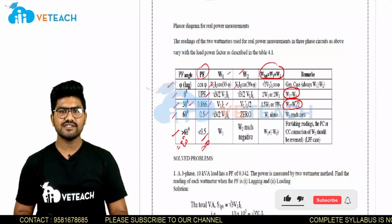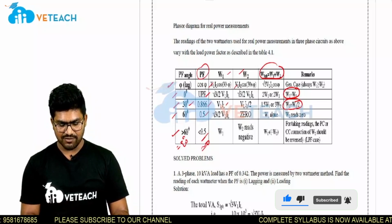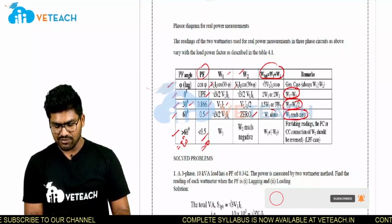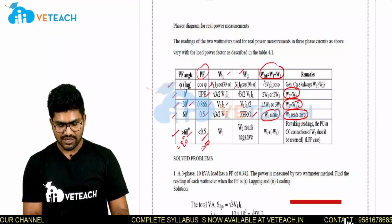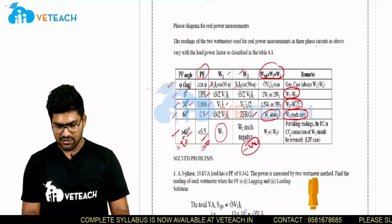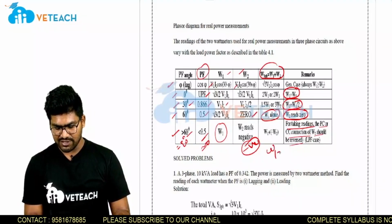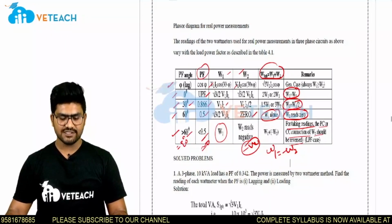Now when the power factor angle is 60 degree, we get root 3 by 2 VL IL as W1, but W2 is 0, right? So here W2 reads 0 and W1 alone acts. Now when it is greater than 60 degree, W2 reads a negative value, right? So for taking readings, the PC or CC connection of W2 should be reversed. W1 is nothing but minus W2 if the power factor angle is greater than 60.